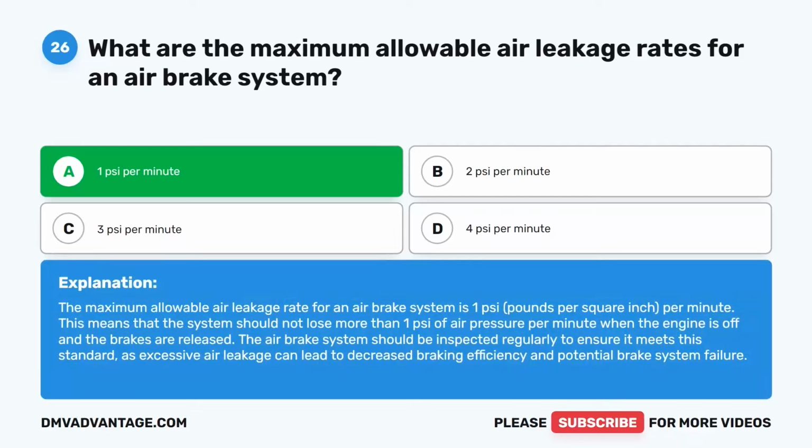The maximum allowable air leakage rate for an air brake system is 1 psi per minute. This means that the system should not lose more than 1 psi of air pressure per minute when the engine is off and the brakes are released. The air brake system should be inspected regularly to ensure it meets this standard, as excessive air leakage can lead to decreased braking efficiency and potential brake system failure.